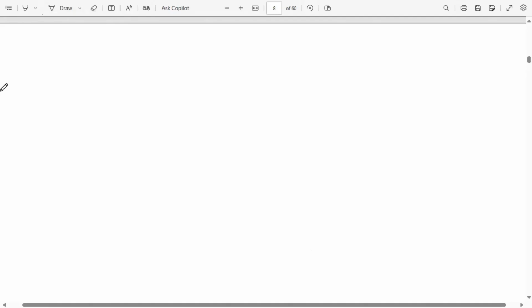stress shielding prevention, because if the implant is too stiff, let's say it has a high Young's modulus, it is going to be carrying most of the load, hence reducing the stress on the surrounding bone, leading to bone loss. There is a condition that we call osteopenia, which basically means bone loss over time, because almost all the load is carried by the alloy. Since it is very stiff, it has a higher modulus than the actual bone.